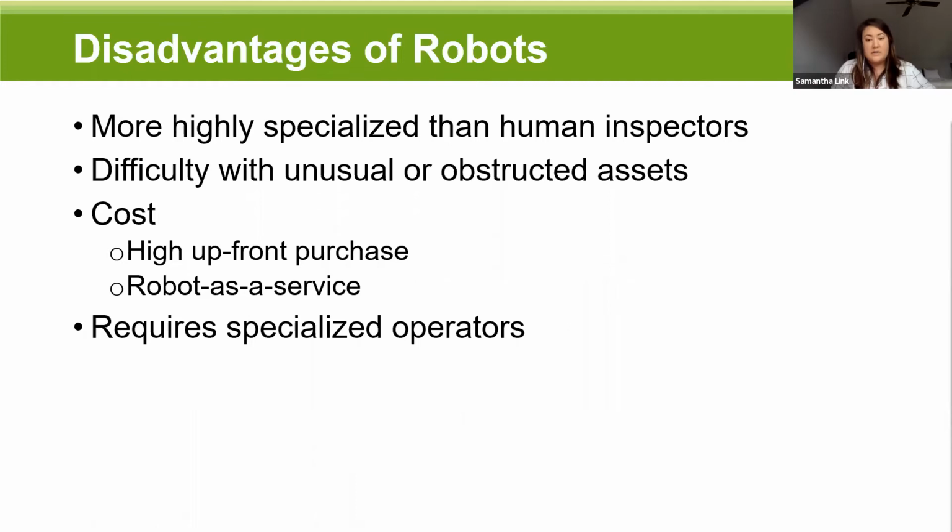So the crawler robot you talked about, can the crawler get reliable data without cleaning for a recovery boiler? Yeah, so the answer is we'd probably have to see the condition of the surface first to be able to give a real answer on that. But for the most part, our expectation is still that there would be a water wash done on a recovery boiler prior to us putting the robot in. There doesn't need to be additional cleaning or grinding done like you might have to do with manual inspection. However, it would need to be just water washed prior to us coming in for a recovery boiler.